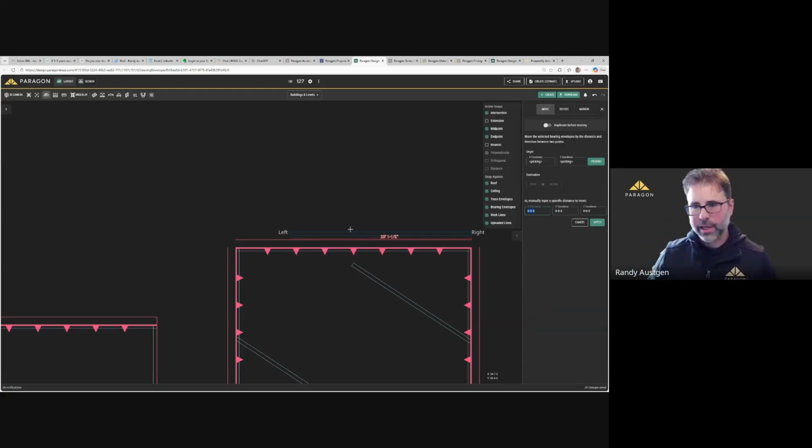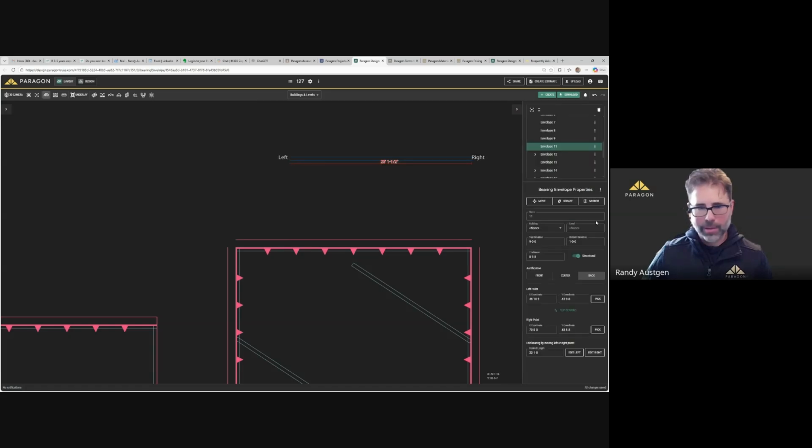I'm going to do this again in a different way. Let's say you're trying to move it according to dimensions on your plan. You've got a 10-foot dimension. I'll say 10, and then come to the bottom side of a dimension, so I could say minus 3'0"8, and there we go. It does the math: 9 foot 8 and a half, and it moves it by that much.